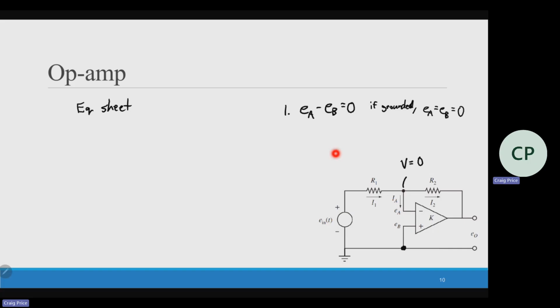By knowing this, I have input voltage, and then I go across the resistor, and I'm back to 0. So you have that relationship. It's like a simplified KVL. I don't have to do the whole loop, just going from 0 volts to 0 volts. Same thing on the right-hand side. I'm going from 0 volts, then I drop across the resistor, and I drop to E_out. So there's a relationship there as well.